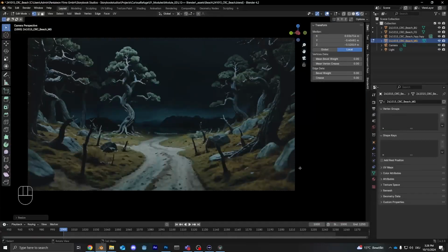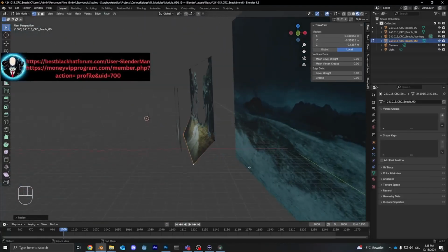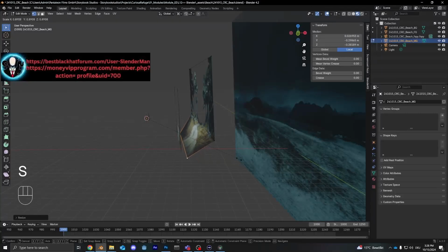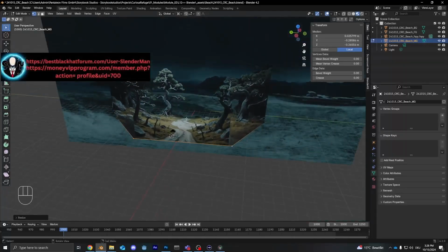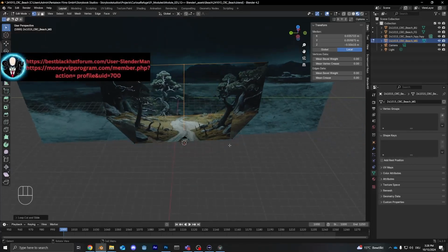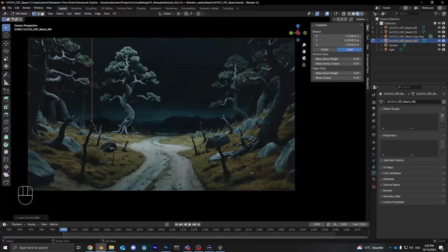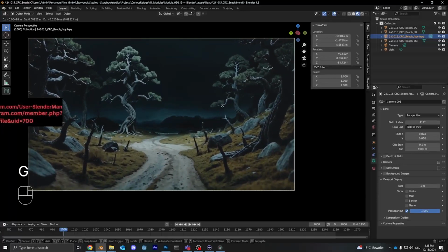And we'll see the effect by going into the camera. It's going to warp a little bit, but not as much as we think. So that way, we're actually tricking the perspective a teeny bit. Now, you see it did actually warp. And the reason for that is just the resolution. So if you want to fix that warp, you can just add another loop like this. If you click, you'll see it'll warp right back. If you still don't like what it looks like, you can just keep adding them and it'll fix that step by step. And now if we go into the camera, you can actually see by moving it, it's no longer that much of an issue.